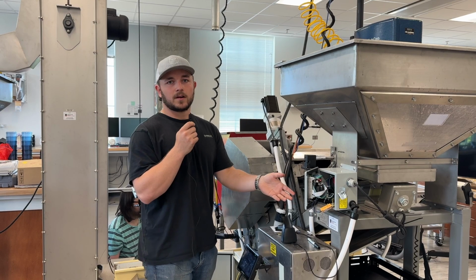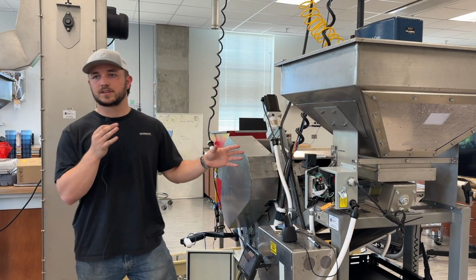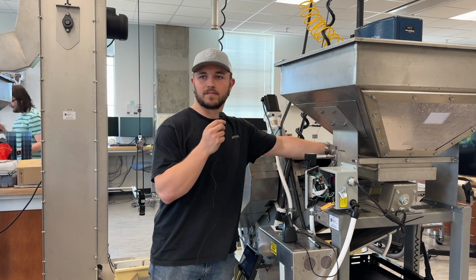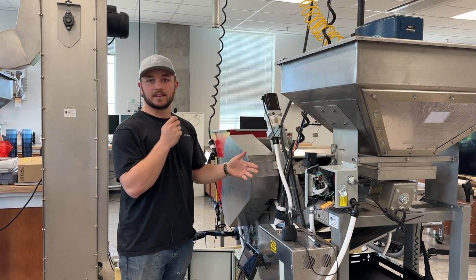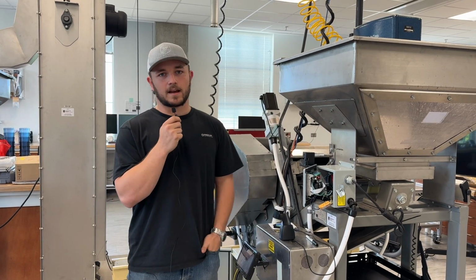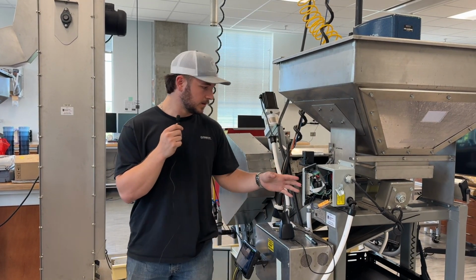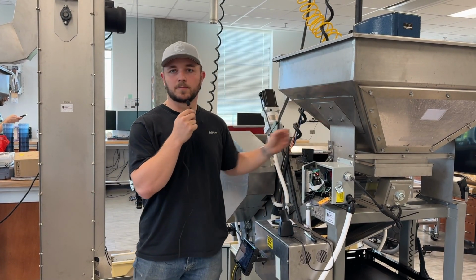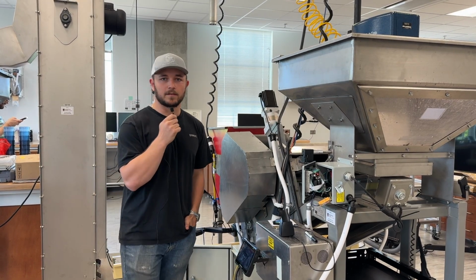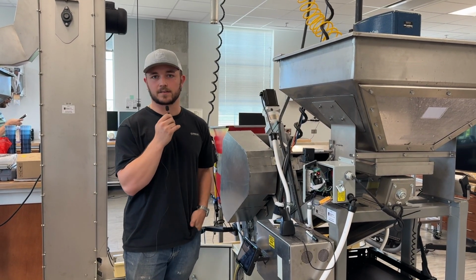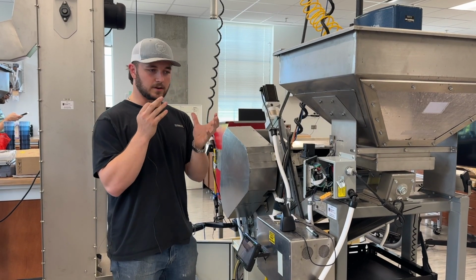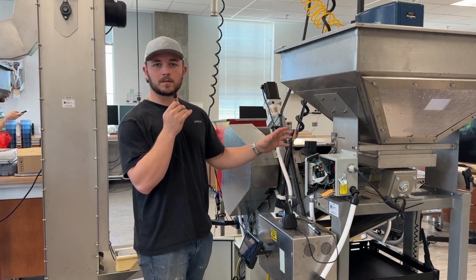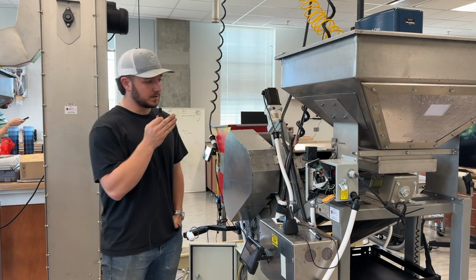In doing so, we found that shell moisture and the surface dynamics of shell moisture moving down this conveyor as it was vibrating had significant impact on your throughput. We found this out because one day when we were trying to connect the power units here with the throughput numbers, we had to stop for a demonstration for about 30 minutes. So those pecans had about 30 minutes to sit there and dry. When we picked up at the same power unit, we found that our throughput had changed pretty dramatically. We realized there was something there.